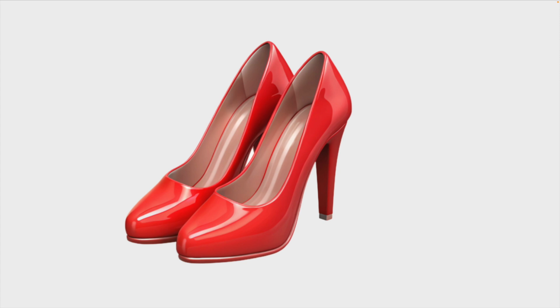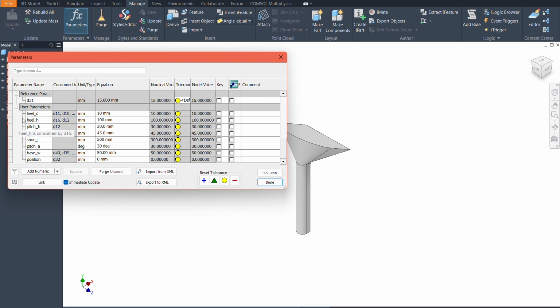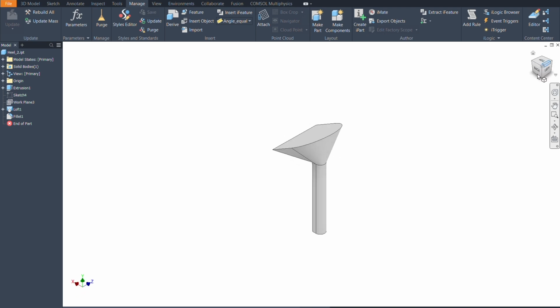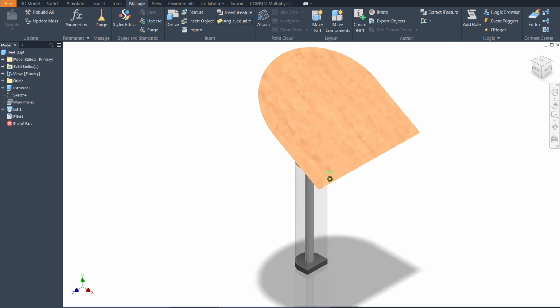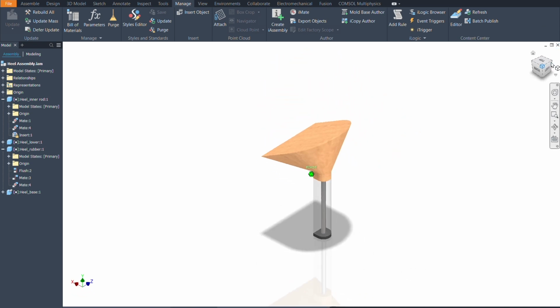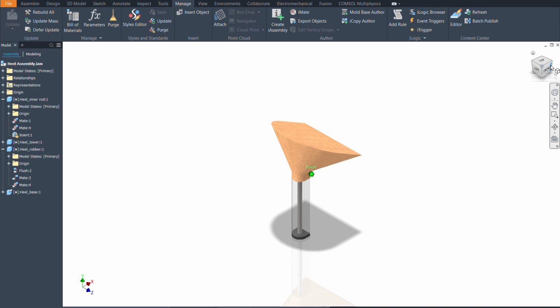The physics themselves are relatively straightforward, until it breaks. But then comes the matter of parameters and force calculation. As mentioned before, the study will analyze the effects of heel height, heel width, and heel position. Lower, thicker heels would mean lower center of gravity and more stability. But we want to investigate where these weak points actually occur and potentially what materials we would need for these regions. Varying the parameters will also highlight the greatest rate of change, a design boundary with risks.